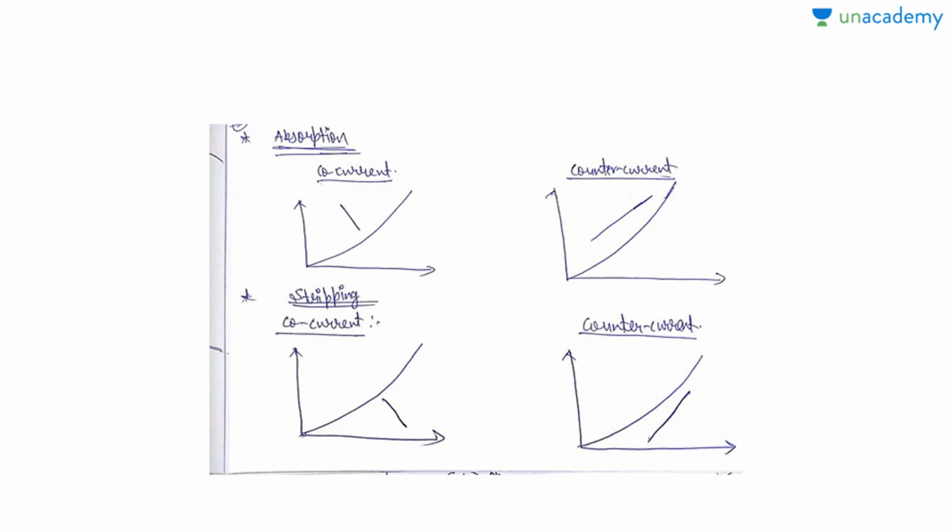We said that for the counter-current operation, the region of the driving force, or the shaded area which we observed in the graphs, will be more. That is why in industries you might have seen that mostly counter-current operation mode is used when compared to the co-current mode.